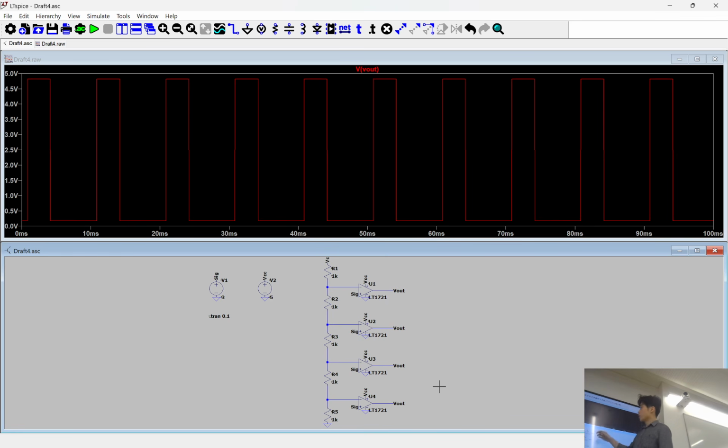Right? So a little bit of voltage will be lost across the first resistor, and that'll become the first reference point. A little more voltage gets lost across the second resistor, and that gives us the next reference point. So we'll have several reference points, right? And then my signal gets compared with each of these.